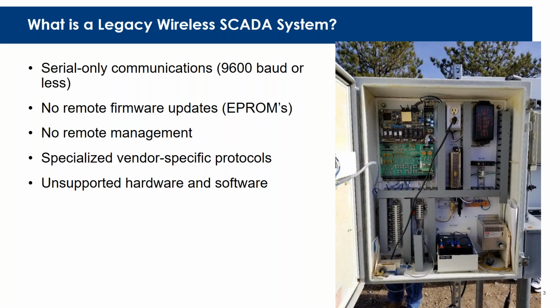What makes them legacy here is that it's serial-only communications. 9600 baud is typically the max. There's no way to remotely update firmware. You'll notice that they're using handwritten EPROMs in this case. There's no remote management to know what's happening with that remote area or that device that's being monitored or managed. And oftentimes these are hardware and software solutions that are no longer supported, so they're just not available to update or buy spare parts for or basically maintain. So it becomes a critical support and maintenance effort to migrate from these legacy systems over to a modern system.